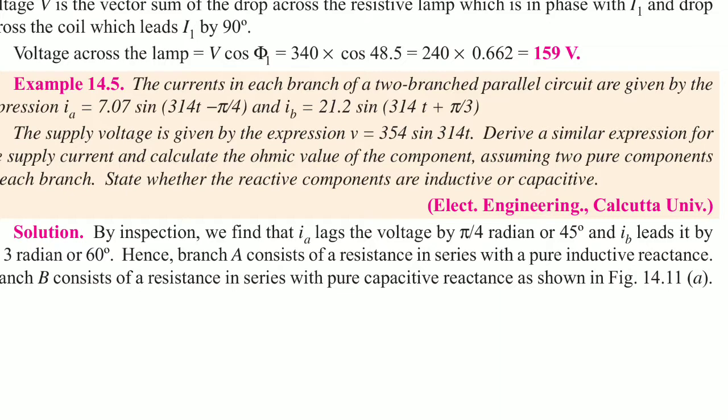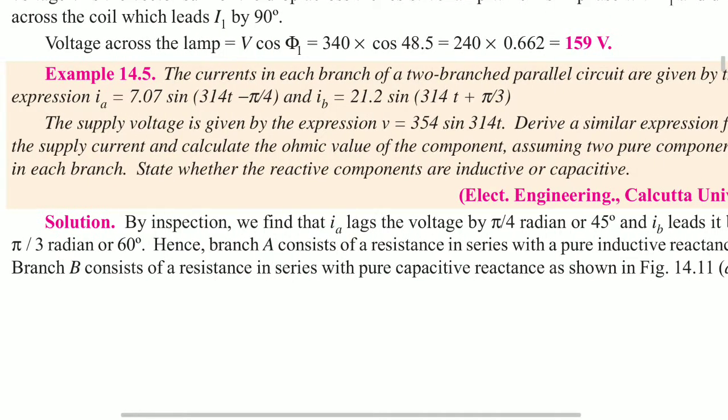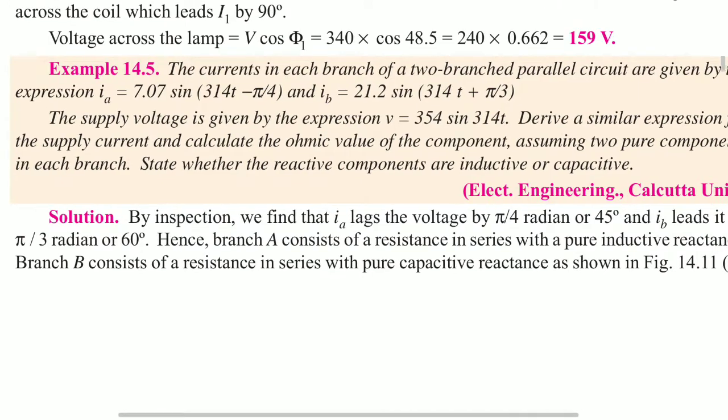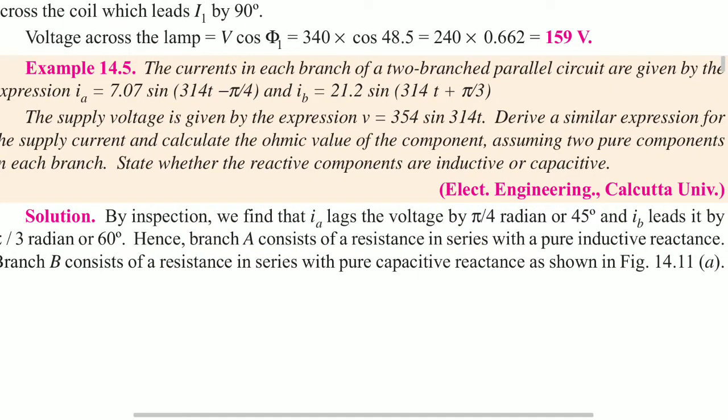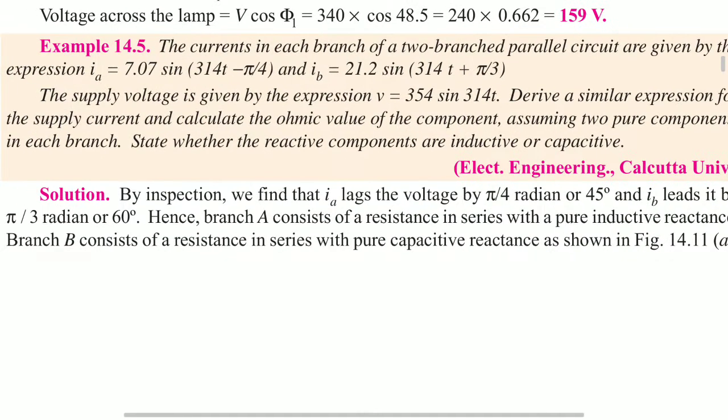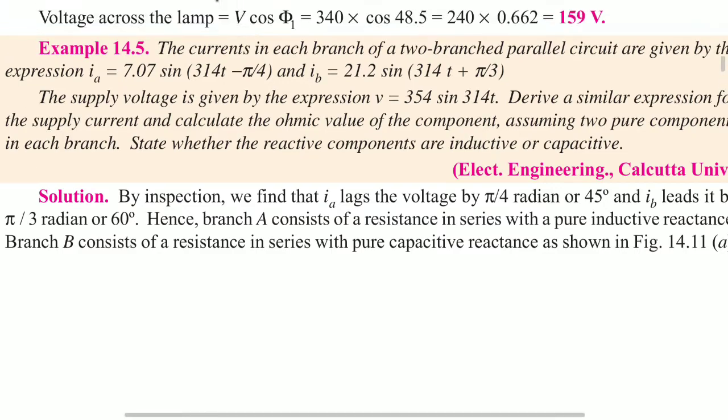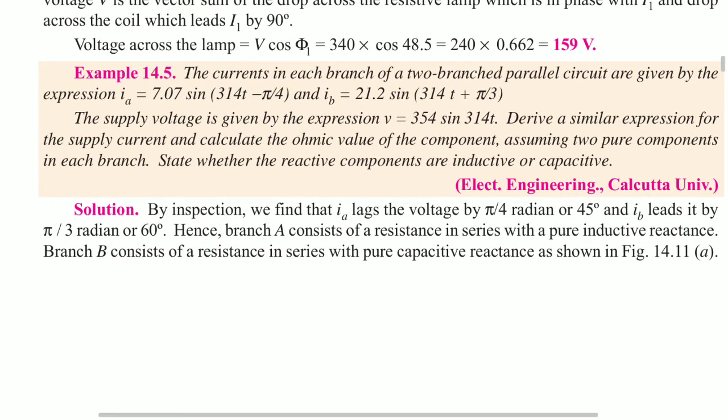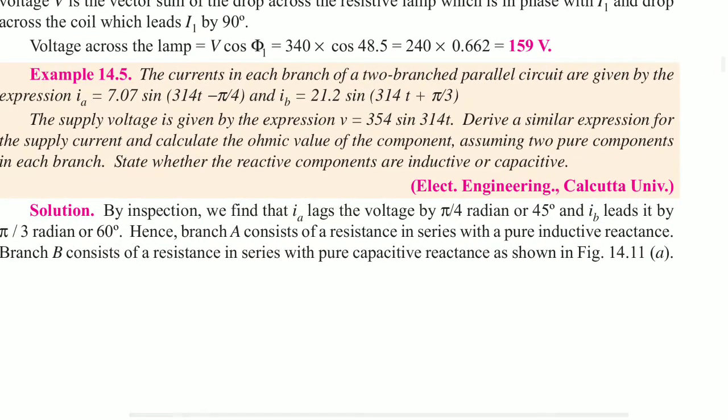So we can say the resultant current is in terms of positive angle only. That means it is a leading current. That is a technique: from these two currents we can say whether the circuit is inductive or capacitive.